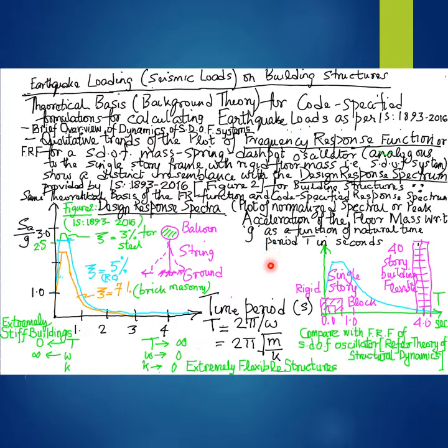Now, it is equally interesting to derive physical interpretation or physical understanding of the seismic response of building structures that lie on the other extreme of the design response spectrum, that is, the extreme wherein the time period, that is the natural period or the fundamental time period capital T, tends to infinity.